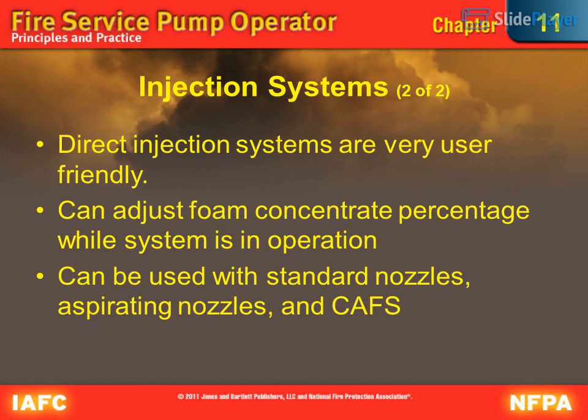Direct injection systems are very user-friendly. Can adjust foam concentrate percentage while system is in operation. Can be used with standard nozzles, aspirating nozzles, and CAFS.